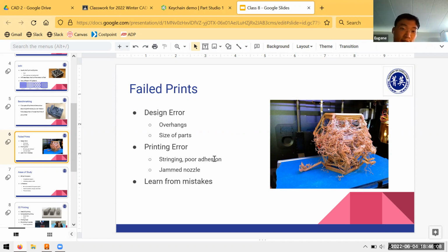It could have been during the design phase, when you're still in Onshape or whatever CAD program and creating your design. So you want to see, did I design something not very good for 3D printing? Like, no matter how I orient it, there are going to be really severe overhangs. Or is it a feature that's way too small on some part of my geometry? Things like that.